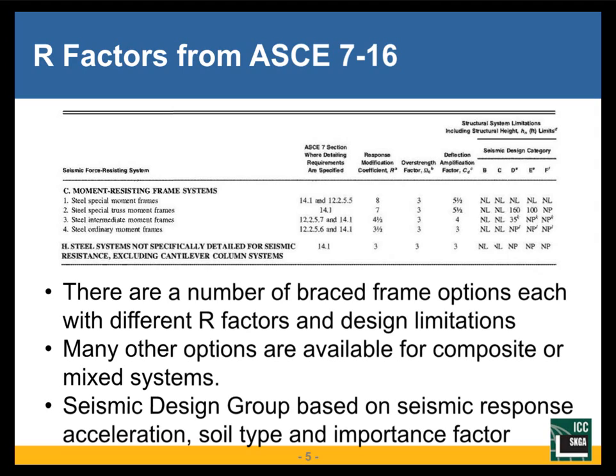If you look at the document, ASCE 7-16, one of the key items that we have is this table in ASCE 7-16 defining the R values for the system. This table is quite important because it defines when you can use the equivalent lateral force method and the tools for using it. I think if you look in the table, you'll find that, first of all, there's a reference showing portions of ASCE 7 that might specifically address this variation.